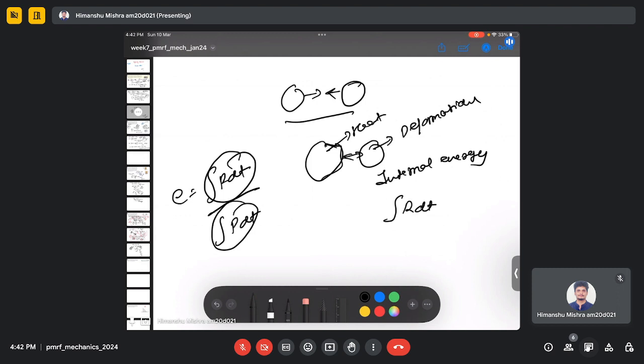So in order to describe the system, you need conservation of linear momentum to define the unknown force or unknown velocity. You can use the conservation of energy as a proxy along with the conservation of momentum, but you cannot use only conservation of energy to calculate the unknown, because it cannot describe all the forces acting in the body.